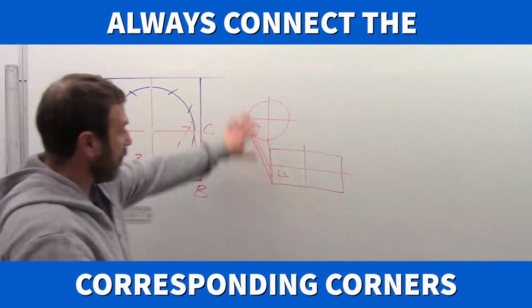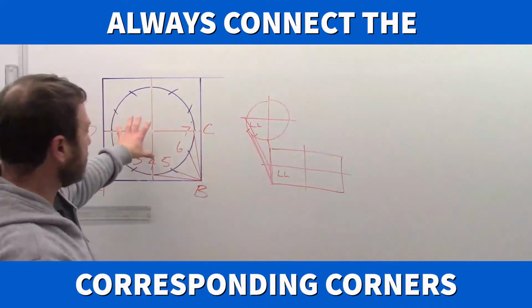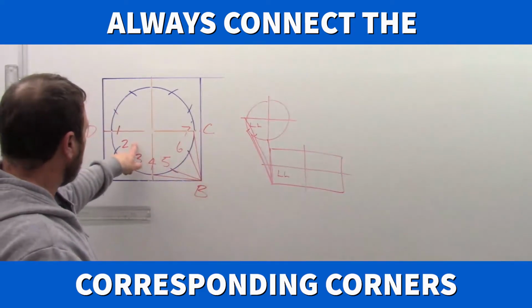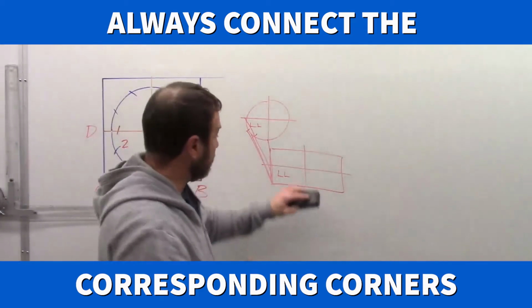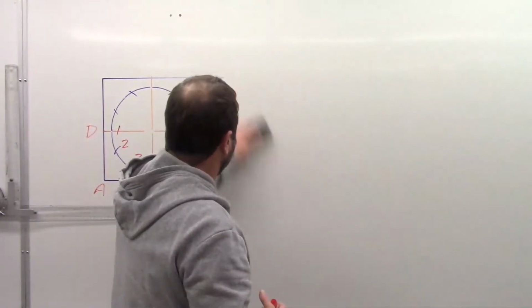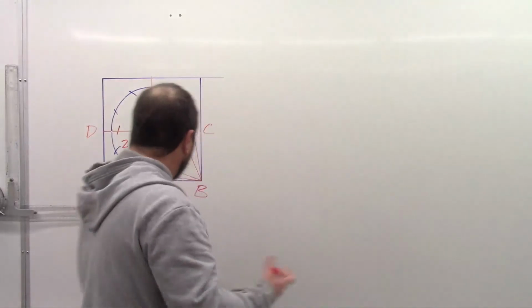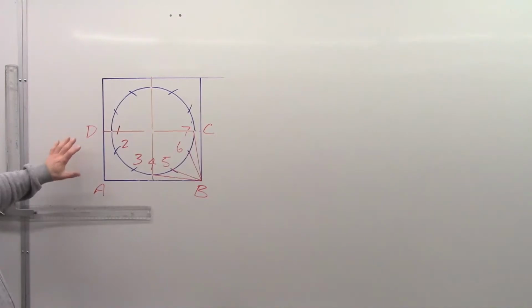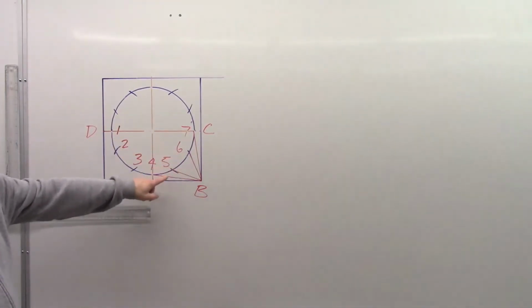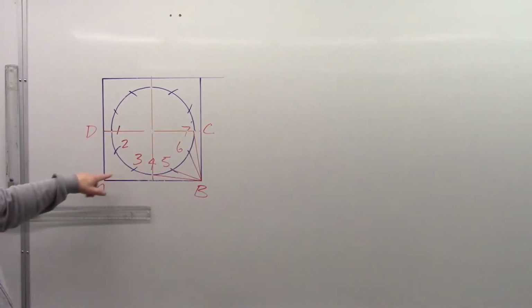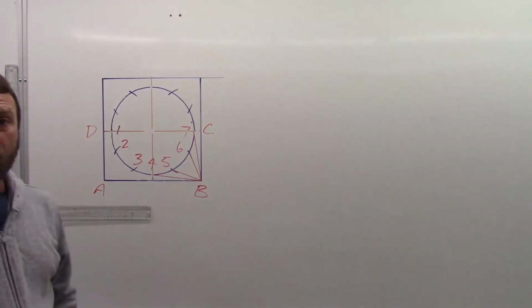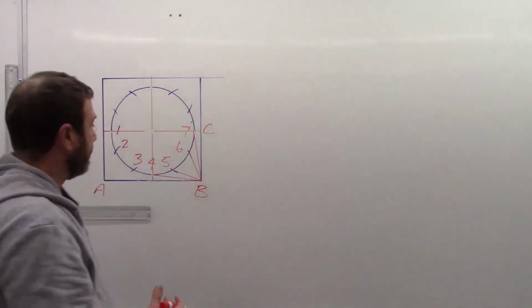Okay, but it doesn't matter where the configuration is, on center or not. Lower right, lower right, lower left, lower left. That's just a general rule for triangulating from plan view. So plan view, that's as far as we need it. We know that this corner is a duplicate, so I haven't drawn in the element lines, but I could just draw them back to A and work it that way. But the next thing we want is what we call a true length diagram.